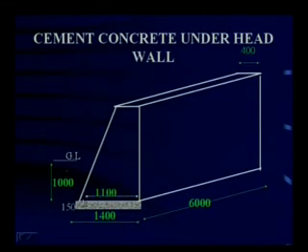And what is the length here? See, this is 1400 mm. This is the width. The width is 1400 mm. The length is 6000 mm. The thickness of PCC is 150 mm. So from this figure, you got all the 3 dimensions.